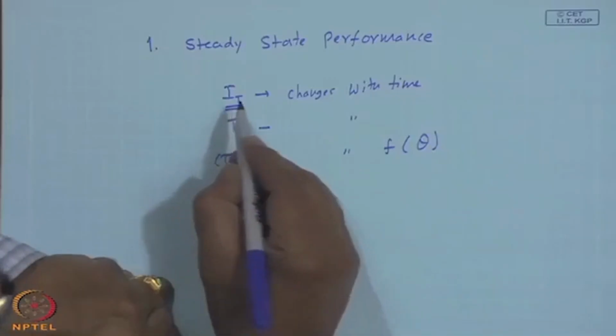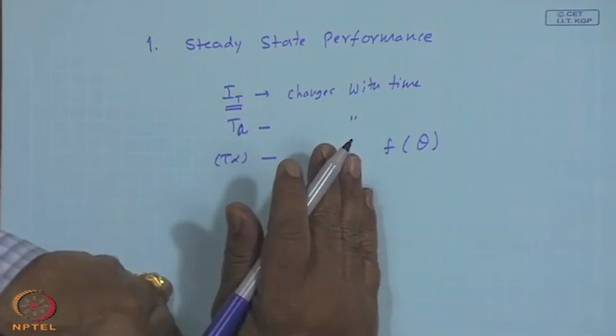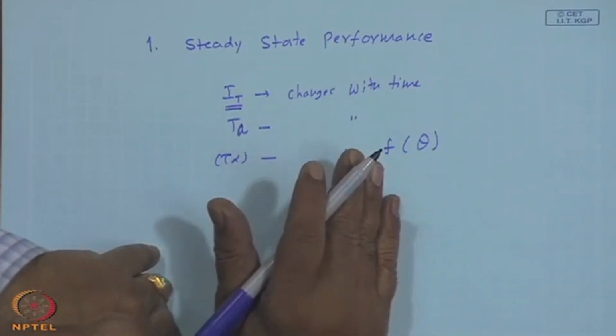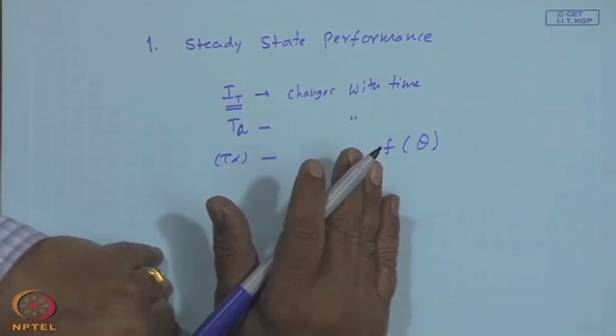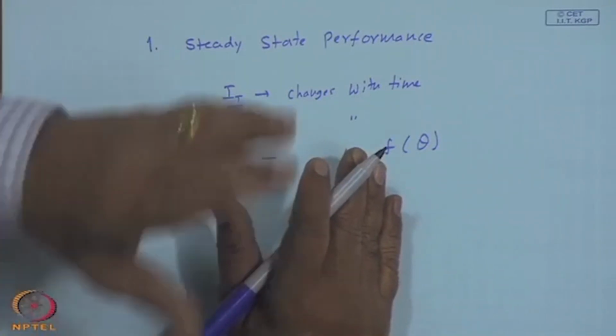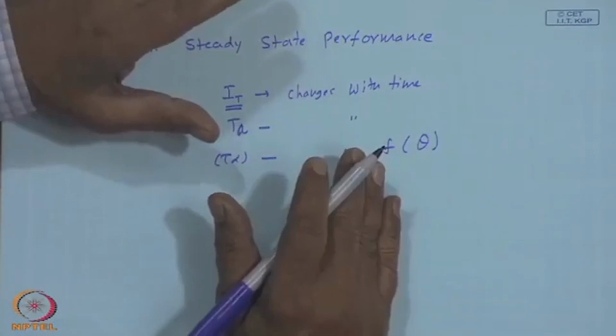In other words, we are trying to obtain what shall be the useful energy gain if a certain intensity of solar radiation, or on a short term scale IT, remains fixed. So, there had been sufficient warm up period and the collector has reached its steady state, and if everything else continued to be so, what will be the useful energy gain?